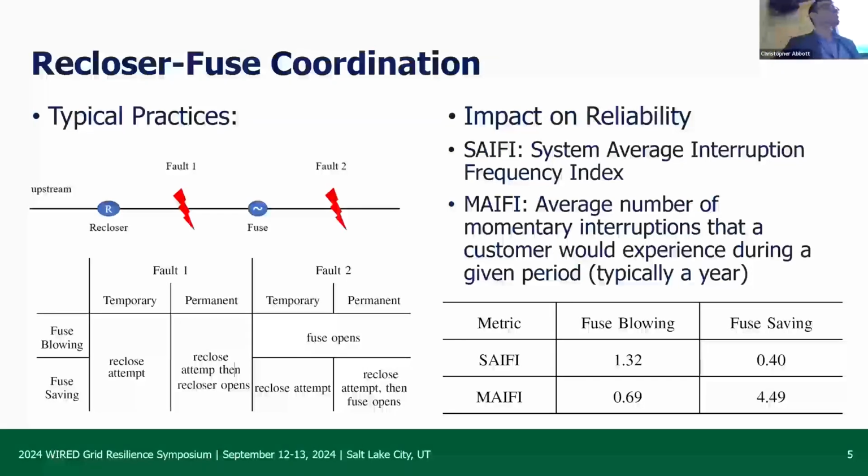What a recloser does is provide the reclosing option. It detects the fault, waits, opens the breaker, then recloses again. Then it waits for 10 to 30 cycles, depending on the number of shots. It could have a single shot or multiple shots. Based on that, if the fault is permanent, it will permanently open the breaker.